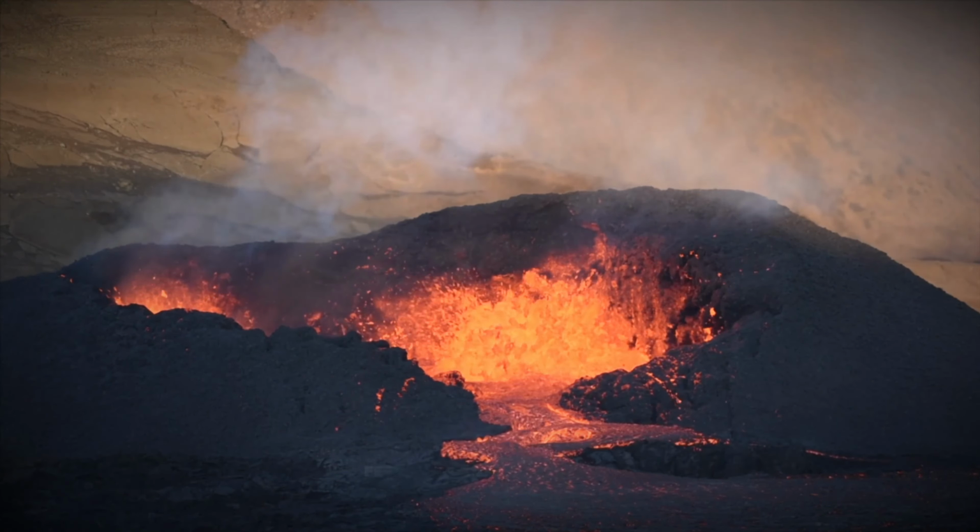The technology. Grinding pyrolysis and integrated drying. Renergy employs a proprietary process called grinding pyrolysis, which integrates two key functions. 1. Simultaneous grinding and pyrolysis. Unlike traditional systems that require very uniform input, grinding pyrolysis allows large or heterogeneous waste particles to be mechanically comminuted, ground, while thermal processing is underway.